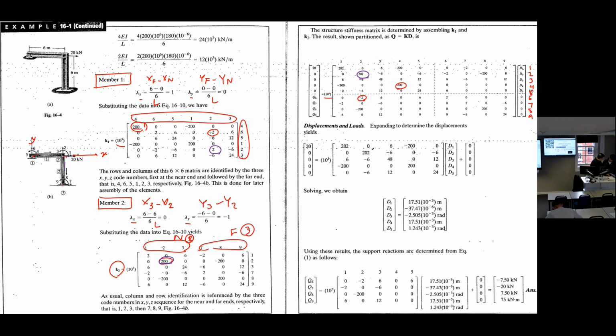If you push a support, you will get a support reaction. Deformation occurs, right? So these go just to support reaction. It's like following this structure, only we do fixed end moment here. But what you get from the analysis, you will have some deformation, and you will have those reactions here. You have two effects, one from the fixed moment at the first stage, plus whatever you have done in your analysis.